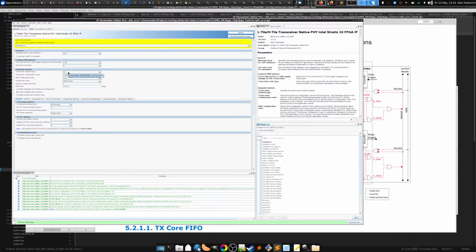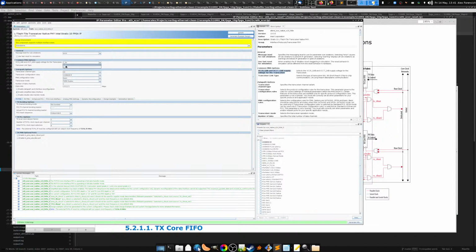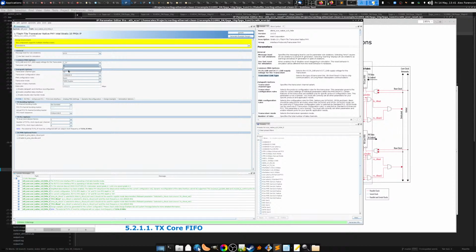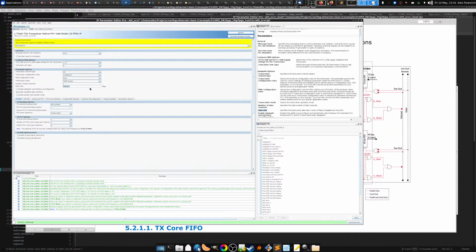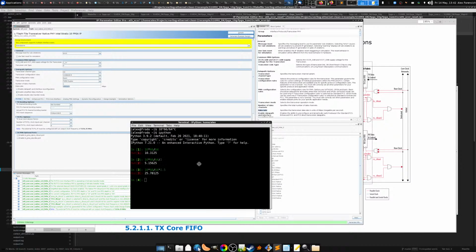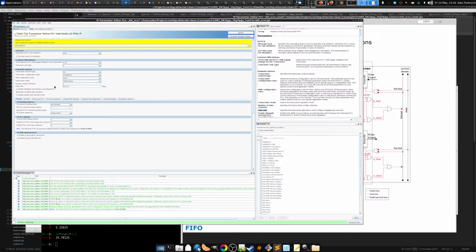But like I said, I want the configuration to also work at 25G. One thing I need to do is change this to 1.1 because that's the actual voltage. And then it's LR. All right, there we go. So for 25G, the rate that I need to run at is a little bit higher. I'm going to multiply this by 2.5, 25.78125. That's the number that I need. So this is 25.78125. Okay, there we go.